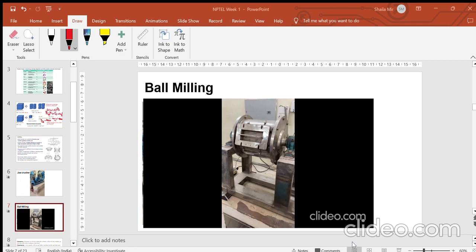Yes. When you go to a ball milling process, based on the forces involved, between the balls there is abrasion, and there is also impact, because the balls will be raised as the ball mill rotates in a circular motion. The balls will be raised to a certain height from which they will be dropped. There will be some impact forces and some abrasion forces acting. So ball milling is always utilized when you already have a crushed powder that needs to be further reduced in size.